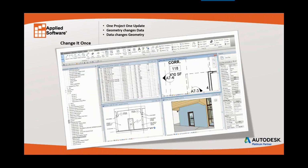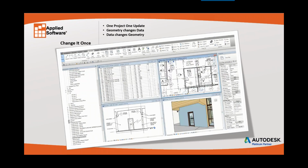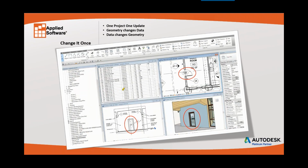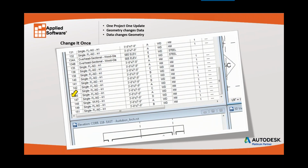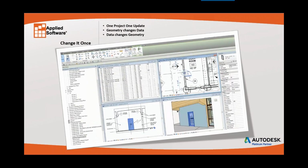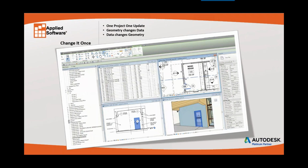So simply what I'm going to do is go into the plan view, select this door right here, the one that's being identified in the schedule as well as a single leaf door. And what I'm going to do is insert another door into the floor plan view. And watch what happens. First I need to move it, and look, it adjusts in the elevation and in the 3D view. Also the tags move with it.